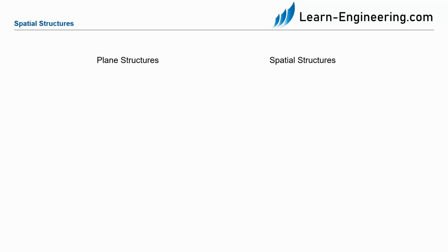First of all, the simple support. This has a support reaction of 1 in both 2-dimensional and 3-dimensional bodies. It is only used to catch translational movement in the axis in which the simple support is attached. The other 2 axes and all 3 rotations are still possible with the simple support.